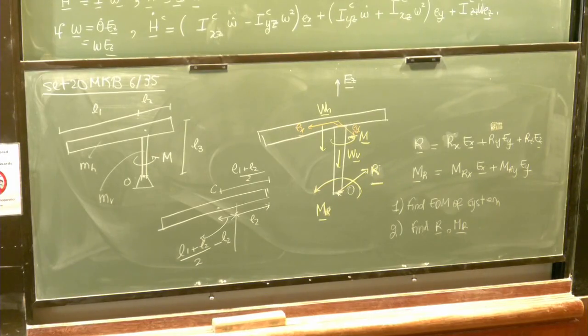Why do you have another one too? And make sure you also have your reaction. One for the vertical, one for the horizontal. Oh, you separated the two sides. Okay, that's fine, but be careful. You have to use feet, not inches. Plus the reaction. You have to add the reaction moment.